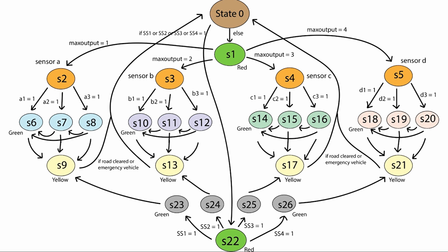Our traffic system also has a camera module to catch any traffic rule violation. Our system has a total of 4 violation detector sensors, RC1, RC2, RC3, RC4. These sensors are present in front of the stoppage line of each road. Thus, during a red signal, all of the vehicles should be behind the stoppage line and the sensor value should be low. But if any vehicle tries to violate the rule and move through, the sensor will be active and the camera module will turn on. The camera will capture the image of the vehicle and send it to Traffic Road Authority for further investigation.